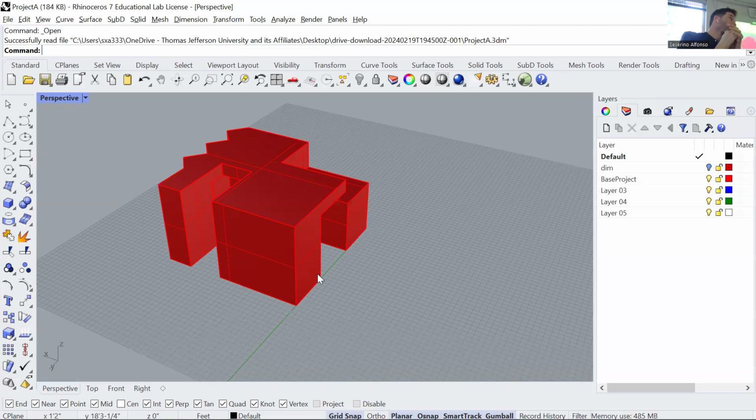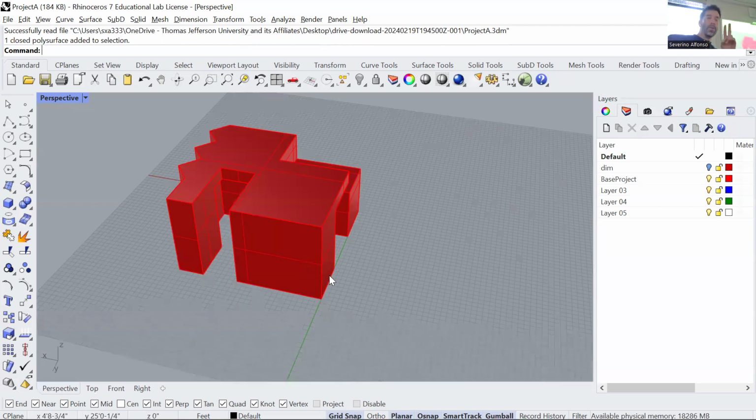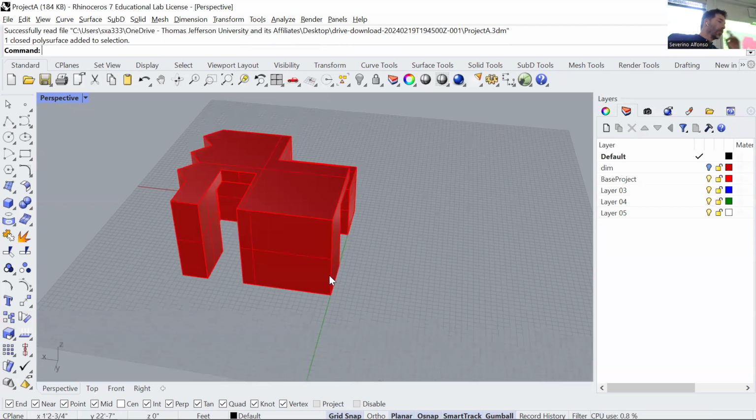Now, it's true that with 3D printing, if it's more affordable, maybe you want to go that way. But if you're going to large scale 3D print, it's going to be a little bit of a nightmare because you're going to have to do multiple pieces and so on. So it would probably make more sense for large scale models to laser cut the shell and then introduce smaller 3D printing components. So this one I'm going to laser cut, and I'm going to talk about two main strategies for laser cutting. One of them is, let's call it, the full body of it. I wanted to laser cut it.